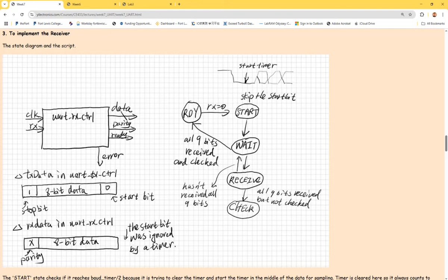It's just one line because TX is shorted to RX. So whenever it's getting pulled down, the receiver can feel it. So it sees a 0 at the receiver's receiving bit or pin. So what's the first thing it should do?